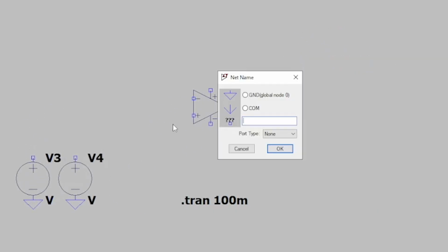Next of all, we have supply voltage. This is a range of voltages you can feed your LM741 without blowing it up, or at least extending its useful life a little bit more. So there you go, kids, don't feed your LM741 with more than 22 volts or else. Now that we have moved from the obvious ones, imagine this situation. Set up a comparator configuration. You feed it 5 and minus 5 volts and input some signals.